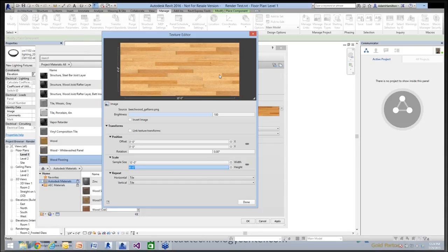The render setup, by the way, we haven't looked at the render window yet, but the low medium res does not tie into the selection of the materials. You can choose the selection of the material. That's all just based on this. Autodesk gives you the 3 different folders so that you can choose, because you could have a low res for concrete, where you don't need a high resolution image. But if you want the wood grain, if you want the marble countertops to have a nice resolution on an image, then use the higher resolution for those. And it also depends on how much you're zoomed in.